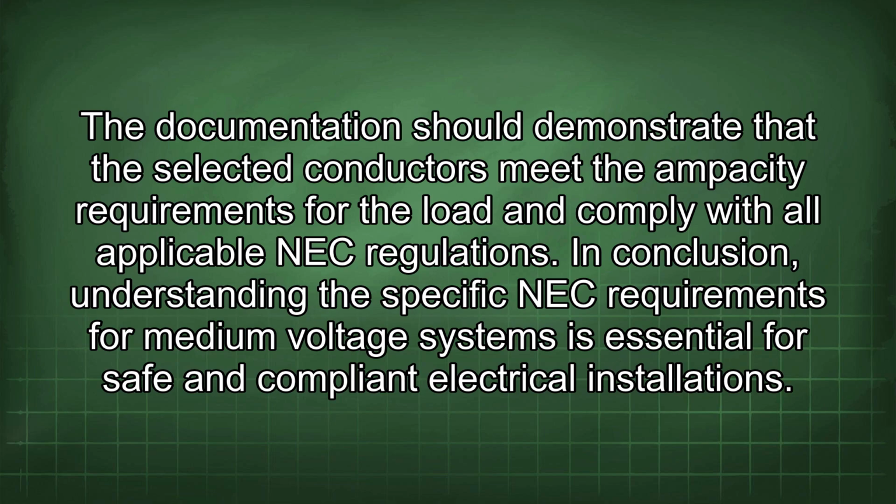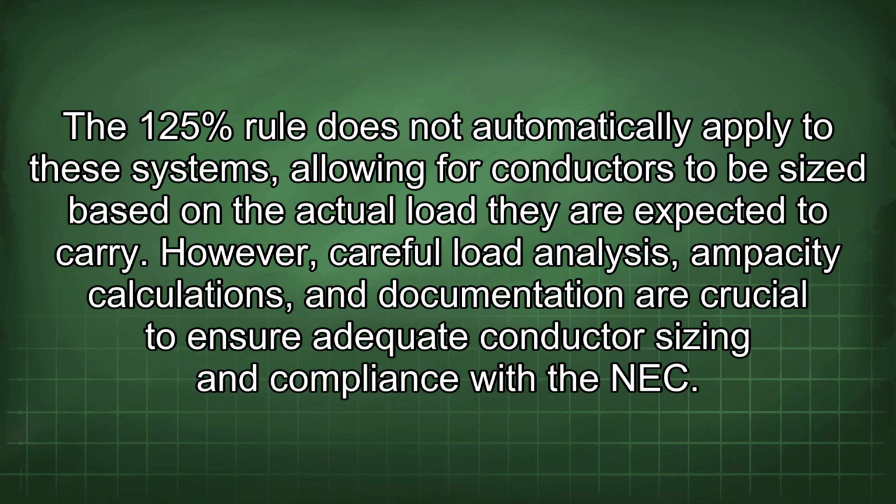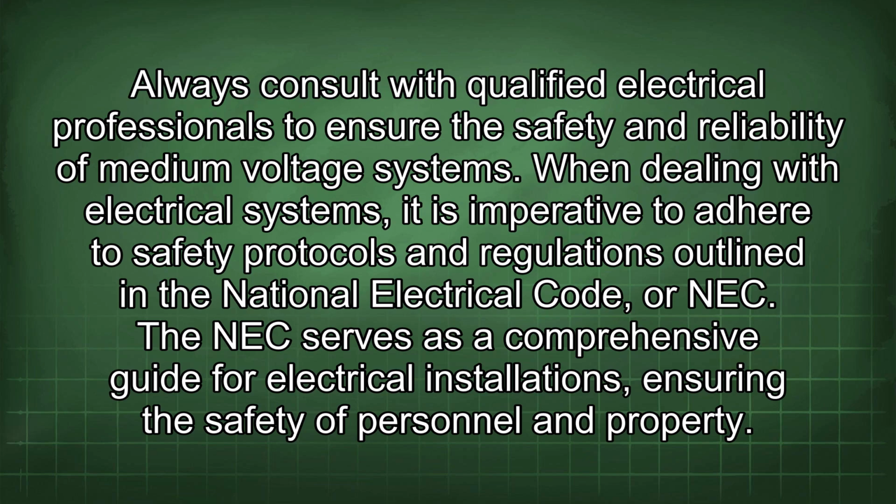NEC regulations. In conclusion, understanding the specific NEC requirements for medium voltage systems is essential for safe and compliant electrical installations. The 125% rule does not automatically apply to these systems, allowing for conductors to be sized based on the actual load they are expected to carry. However, careful load analysis, ampacity calculations, and documentation are crucial to ensure adequate conductor sizing and compliance with the NEC. Always consult with qualified electrical professionals to ensure the safety and reliability of medium voltage systems.